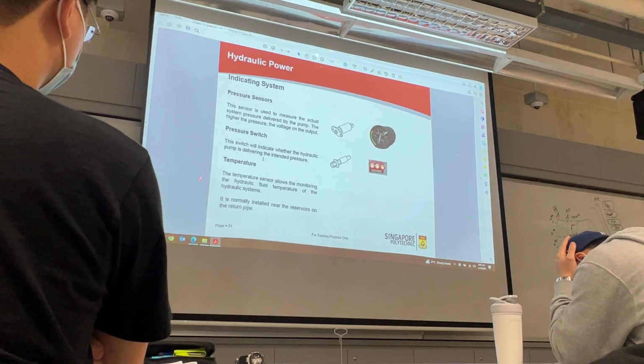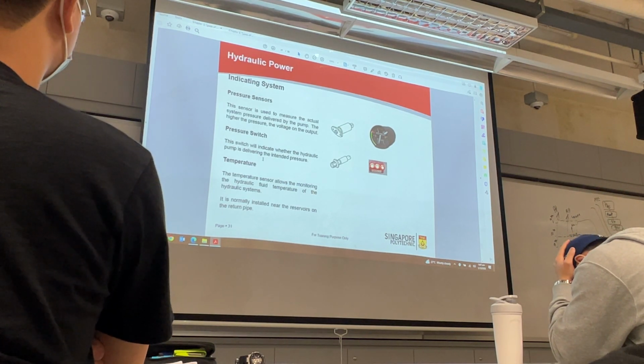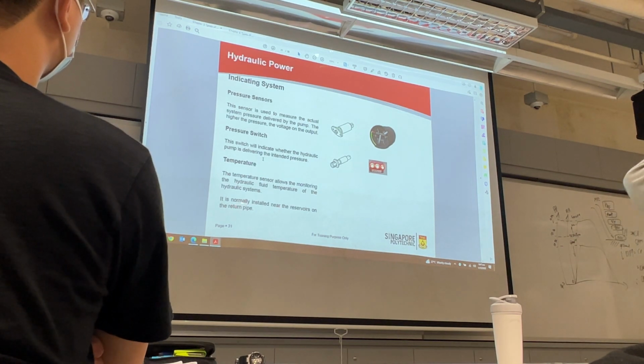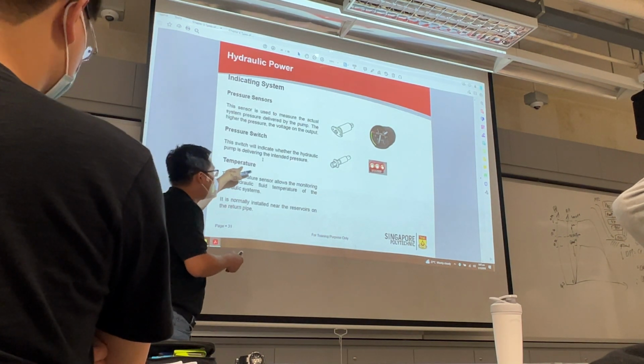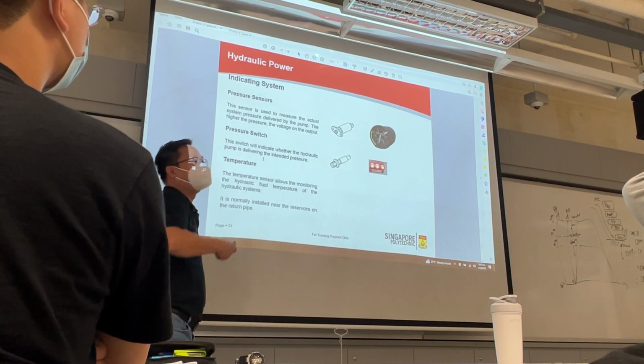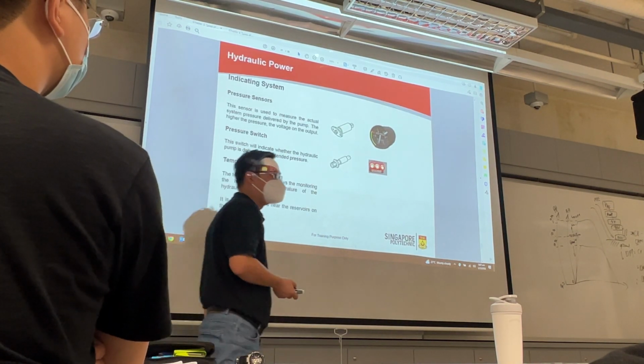Okay? Temperature, we need to know the temperature going back to the reservoir, and it's usually installed on the return pipe. Return, then you need to know. If you put this at the pressure outlet, then what are you looking for? Surely very high, 3000 psi, right? Okay?